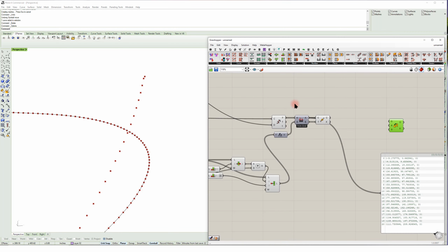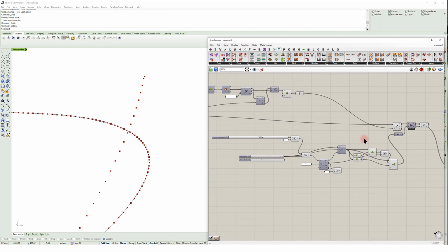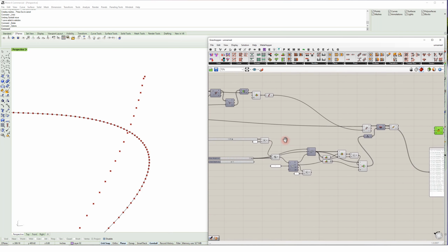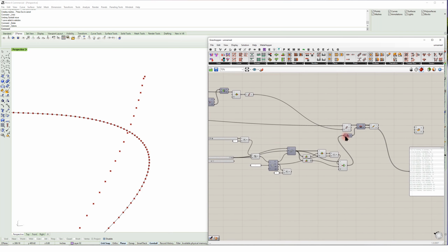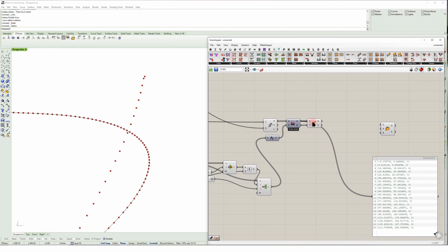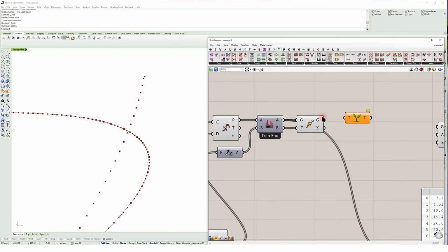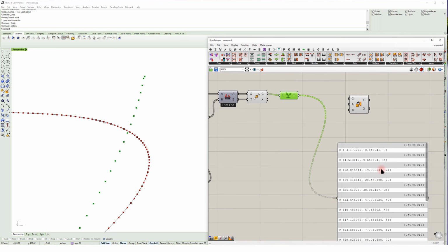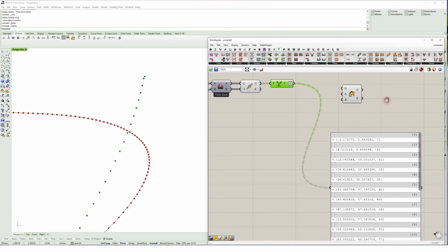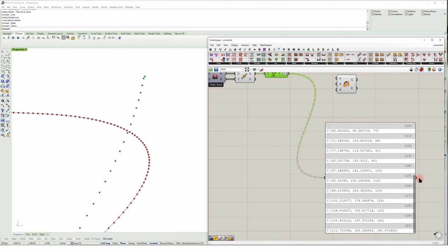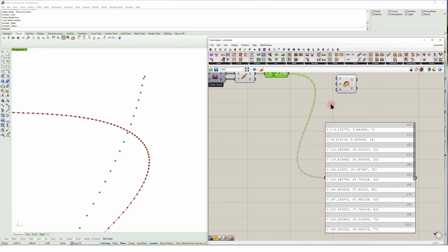Before we go any further, I just want to make sure that we get this all grafted appropriately. So what I want to do now is type in graft, get all of our newly moved points into their own branch right there. And now you can see this is the branch. It's a little complicated, so I'm going to right click on that and simplify. And now we've just got a nice clean set of branches. Okay.